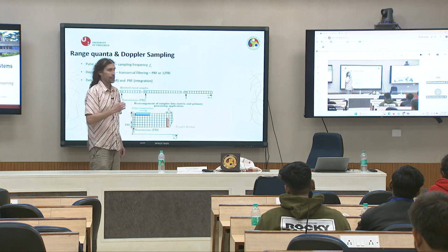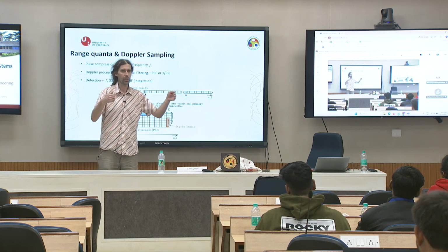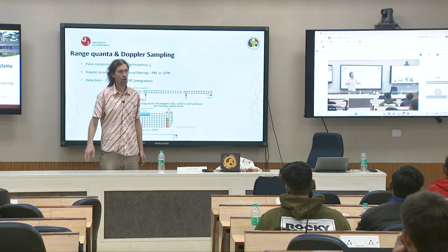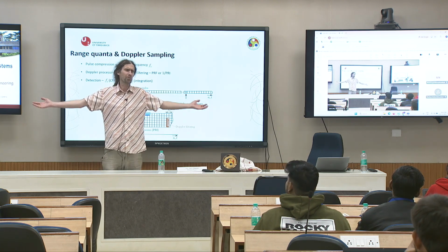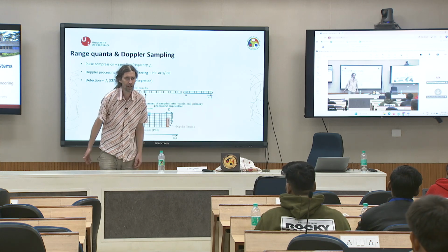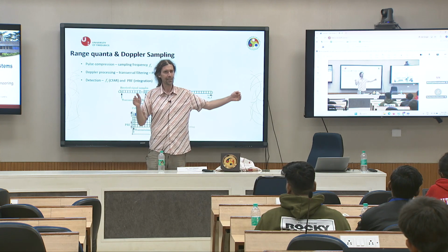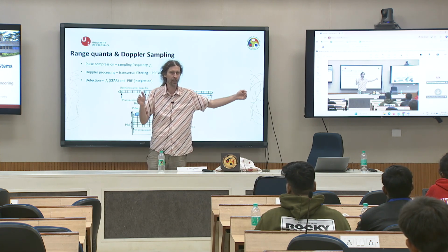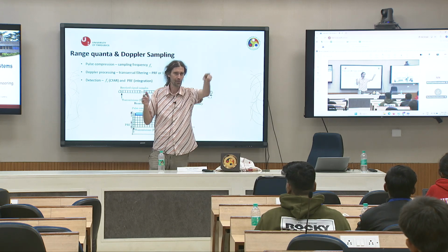And so if the CPI has only 100 samples, how will your spectrum look? Not very good. Why? Because you have only 100 samples, so there will not be much information. So if you have a longer CPI, you will get better resolution in the spectrum.